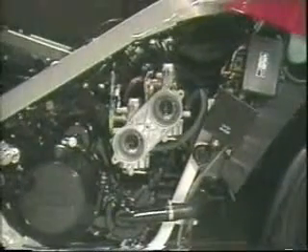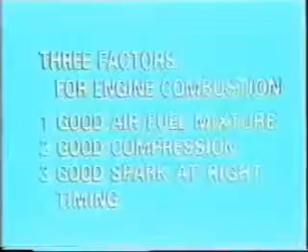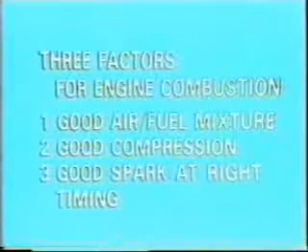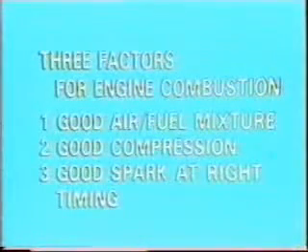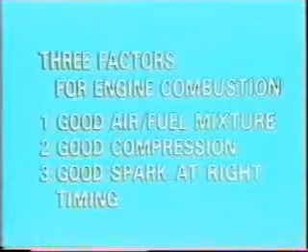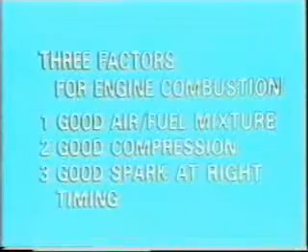Before carburetor troubleshooting, two things must be checked. Is the compression good, and are the sparks good? Only when the answer is yes to these two questions may you begin the carburetor troubleshooting. When the engine does not run smoothly, you must find the throttle opening range of the engine where the trouble starts.